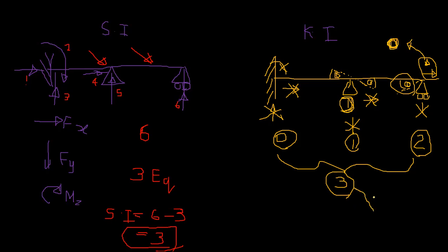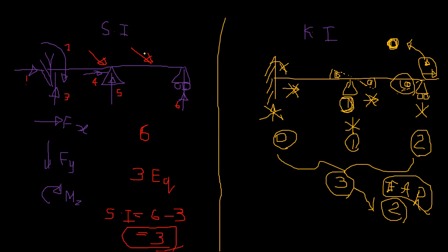So that brings you to, if axially rigid, right? So we will move on with a simple example. Usually if statical indeterminacy is lower than kinematic indeterminacy, the force method is preferred, and vice versa. If kinematic indeterminacy is low, you can use the displacement method, right? So we will get back to a simple example.